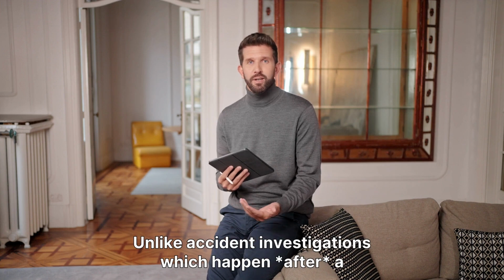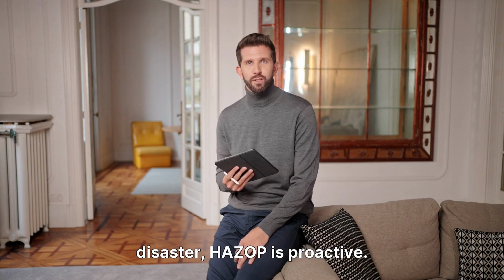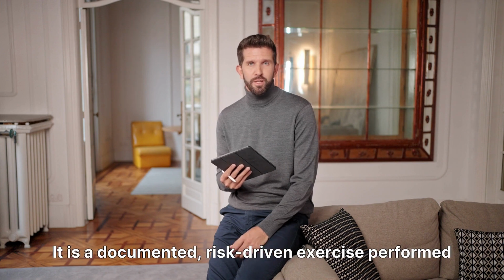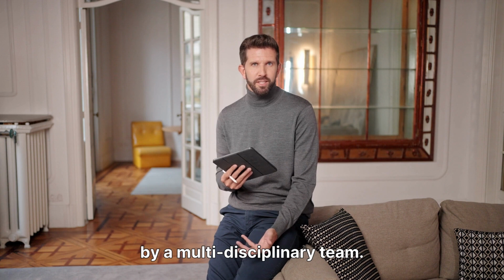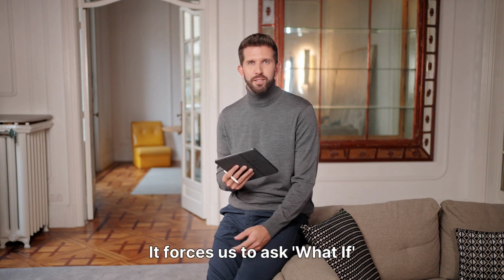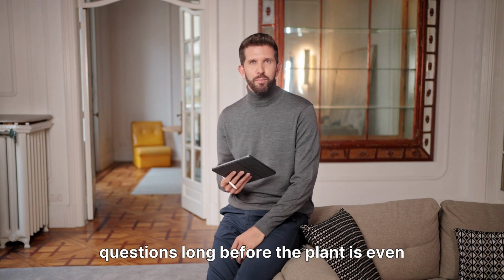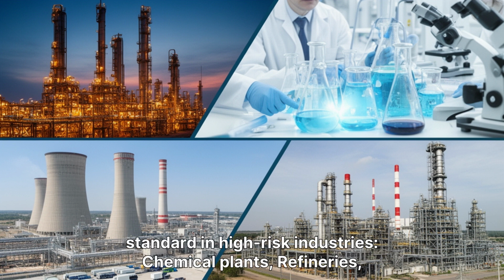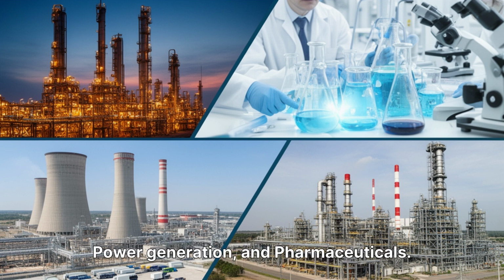Unlike accident investigations, which happen after a disaster, HAZOP is proactive. It is a documented, risk-driven exercise performed by a multidisciplinary team. It forces us to ask "what if" questions long before the plant is even turned on. Because of its effectiveness, HAZOP is the standard in high-risk industries: chemical plants, refineries, power generation, and pharmaceuticals. In these sectors, a small error isn't just an inconvenience. It can be a catastrophe.